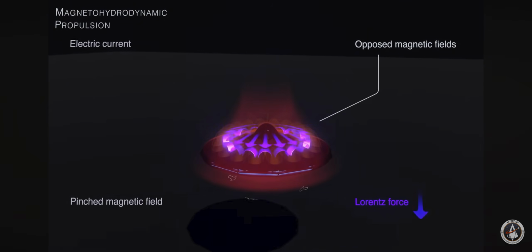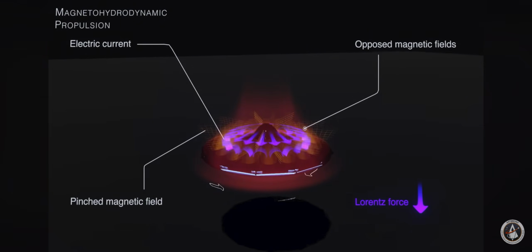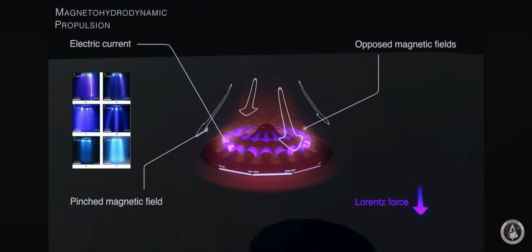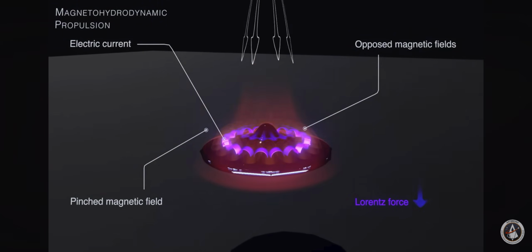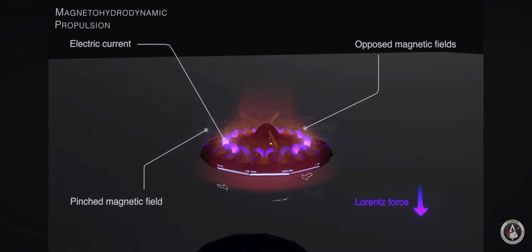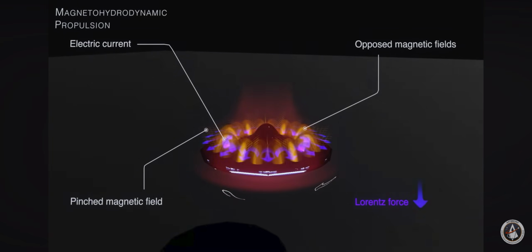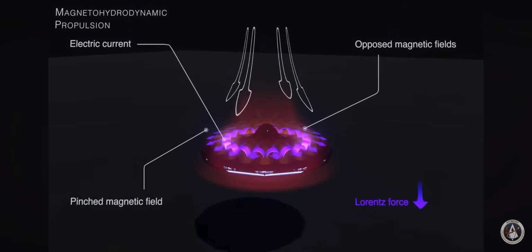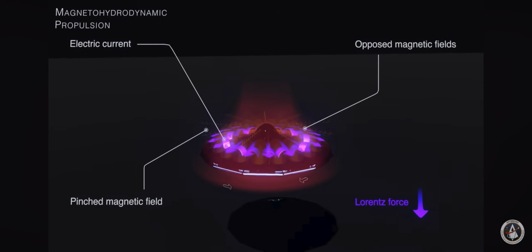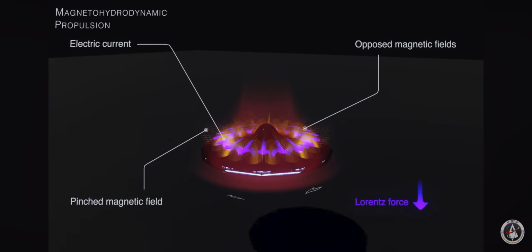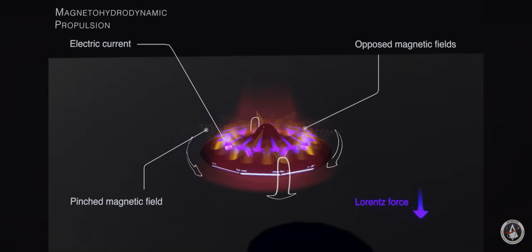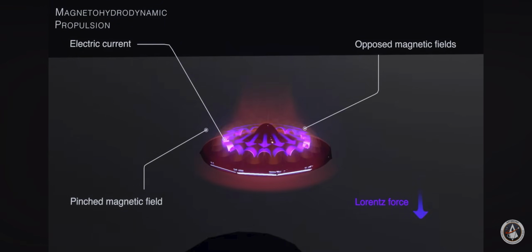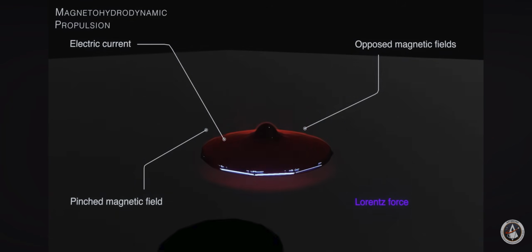This can be done in one of several ways, but one of the most efficient methods is known as high frequency pulse discharge, or HF pulse discharge for short. This is where an alternating current at radio to microwave frequency or higher produces electromagnetic radiation in fields that ionizes air or other gases very efficiently. The ionized air then forms a conductive sheath just off of the surface, which absorbs all or most of the emitted radiation. Once the air is ionized, it can be moved via electromagnetic forces such as the Lorentz Force or via an ion wind effect.